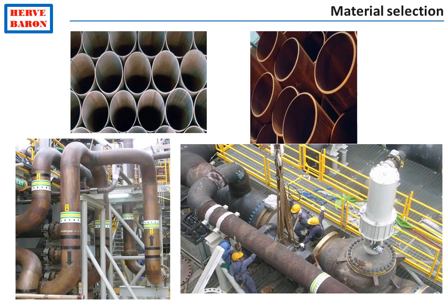In fact, the wall thickness is inversely proportional to the maximum allowable stress of the material, which is its strength. Therefore, a carbon steel twice as strong as an ordinary carbon steel would, for instance, be selected for a high pressure pipeline to halve its thickness.